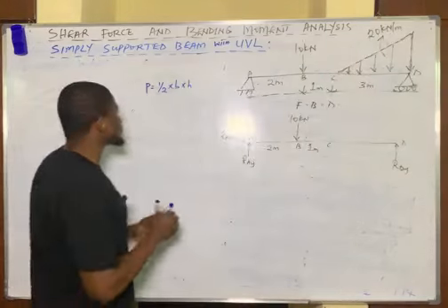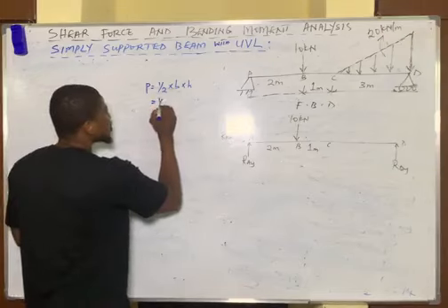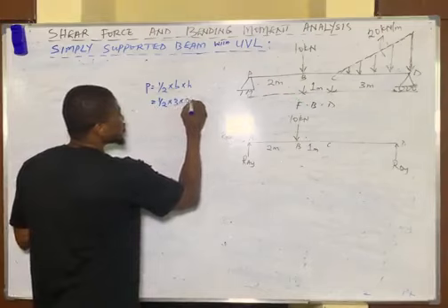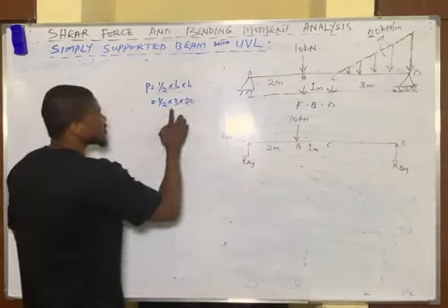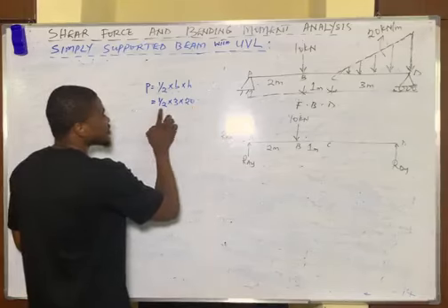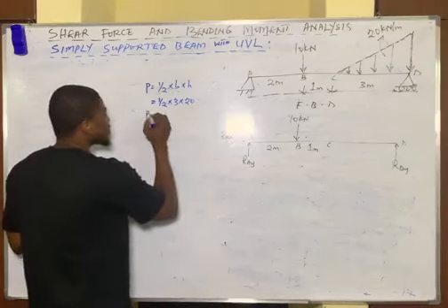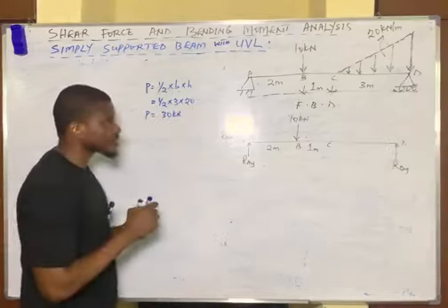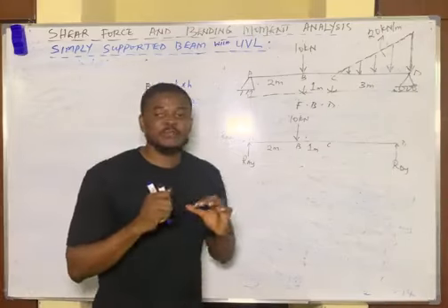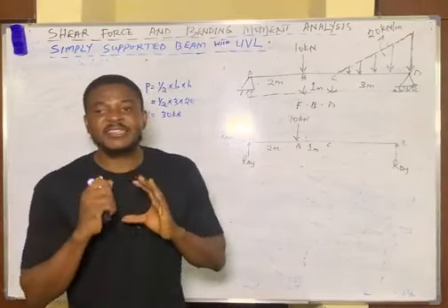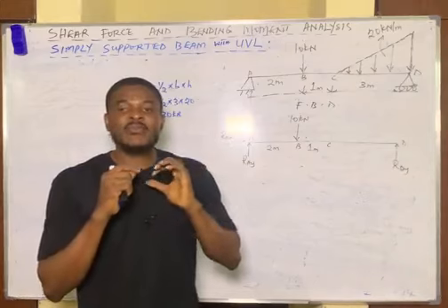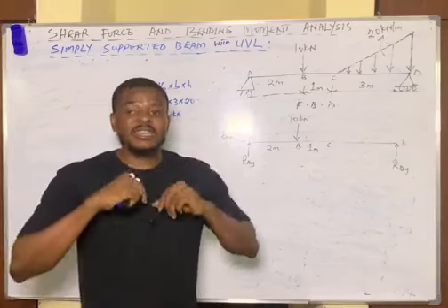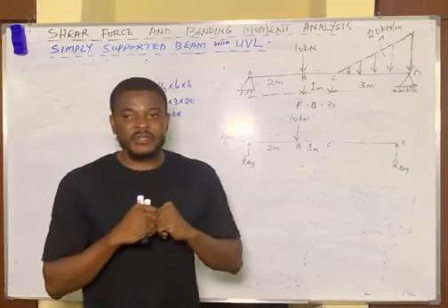So that means this point load is going to be equal to 1 over 2, the base there is 3 meters, the height is the maximum load, which is 20. So you simply have 3 times 20, that's 60, multiplied by 1 over 2. So the point load is actually 30 kilonewtons. Now when you do this, the point load will be placed at a distance 1 over 3 from the base of the UVL, or 2 over 3 of the length from the tip of the UVL.